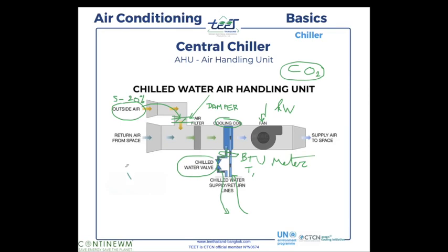Thank you. And the rest of the air is coming from the air return. That means the air that we take from the room that we cooled, from the building that we cooled, and that is processed through the air filter, the cooling coil, and so on.